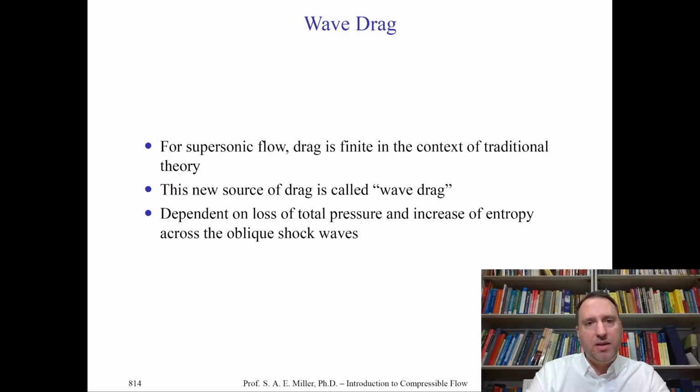Remember, for supersonic flows, the drag will be finite in the context of the traditional theories, of course, inviscid flow. We have discounted viscosity in our flows, but we have relaxed the incompressible assumption and retained compressibility. Therefore, we do find drag, unlike the D'Alembert paradox, which made the assumption of incompressible flow. Indeed, even if our flow is very, very high speed and we forced it to be incompressible, which is unphysical, we would also find zero drag. And so the drag in the inviscid flow is due to the compressibility effects. This is called the wave drag. You can see how it's connected now.